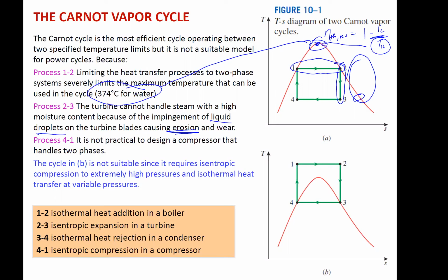Same with if we're compressing. We're raising the pressure on the left. Here we would have a two-phase fluid of mostly liquid and a little bit of vapor, and a compressor doesn't like that. A compressor likes vapor. A pump likes liquid, so a pump could be out here.